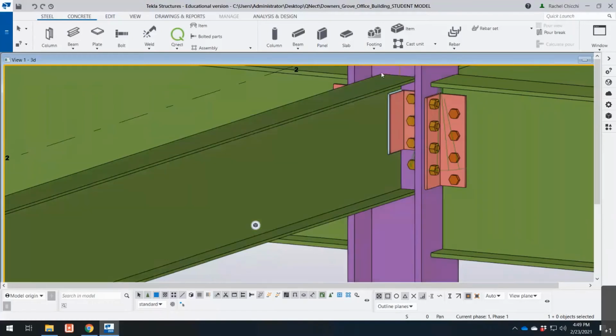There's also room for the angle legs. If you get into column sizes that aren't very deep, you might run into issues doing these double angle connections because you might not be able to get an angle with enough room to be able to fit in there. If your angles can fit, but your beam flange is too wide to fit within the column, what you can do is notch out portions of your flange just as needed to clear the columns so that you can get that beam in there close to the double angles.